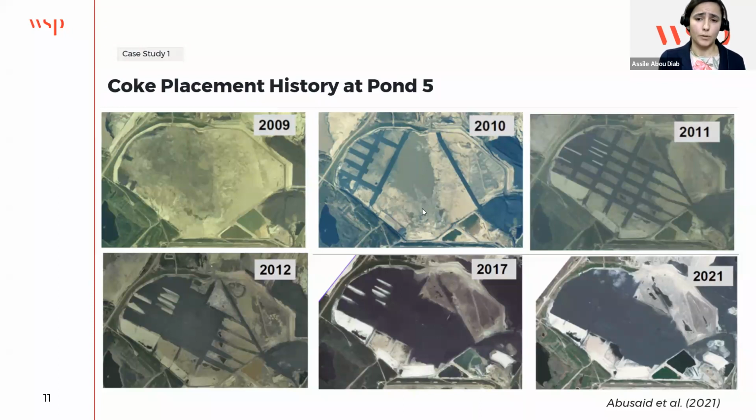They waited until the winter season, because we need thick ice to be able to come on top of the tailings. During winter, they started by putting down geomembranes and geogrids, and they anchored them to the nearby beaches and dikes and into roads.